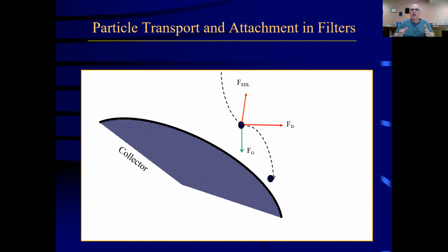Of course, that's something that you have to do: coagulate and flocculate your water properly with the proper coagulant. And it pretty much suggests to you that too little or too much coagulant is going to hurt you. Your job is to make that arrow smaller so that the last arrow, which helps us, called London van der Waals force, can kick in and help us.